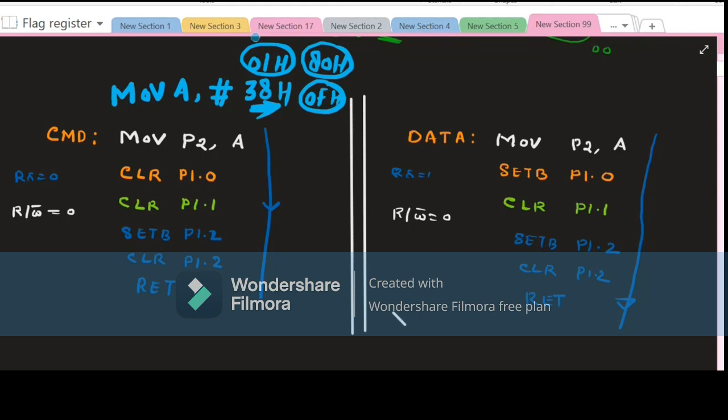One is 06. Okay, sorry, we forgot one, 06. That means increment the cursor. So these are the 5 commands you need to move into your command register. Then only you can send the data. So you have to write these commands or instructions every now and then.